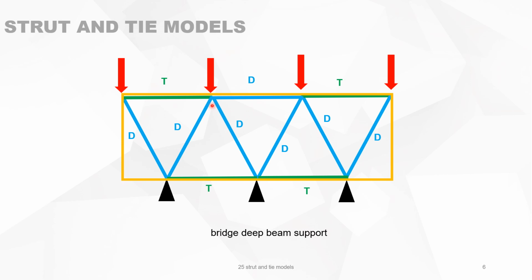This is because this strut and this strut shrink due to the load. It will shrink a little bit, but it will shrink, and this will shrink. So the total length of the strut in the middle shortens. This means that there is compression. Why is this not the case? Because this is shrinking and this is shrinking. So why is this not a compression? Well, this is not hindered. So this can go to the left. That's why this is tension, to prevent this point going to the left and this point going to the right.